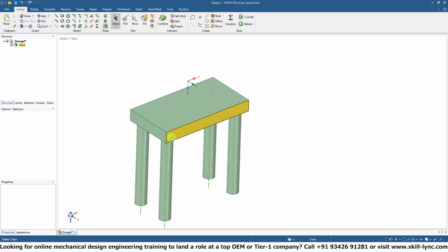So if you have your 3D printer build head, an FDM, and it touches or gives a lateral force onto this leg over here on the top, the torque or the moment that would be experienced on the bottom of the leg would be force times distance away from the rotational point. And as you go up, the distance increases. And so using the formula with the multiplication, it will end up being a much larger force.